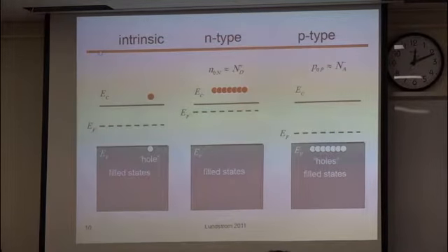Since the number of electrons will be decreased, EF, the Fermi level, which means the energy level at which the electrons can be found with half possibility, will be decreased by the same logic as I explained for N-type silicon.